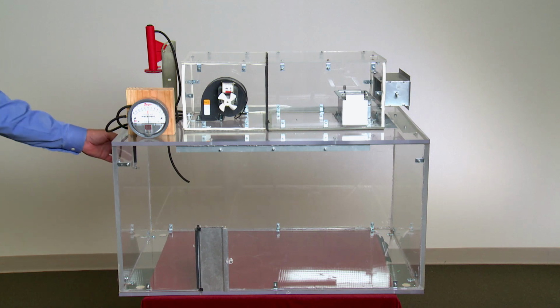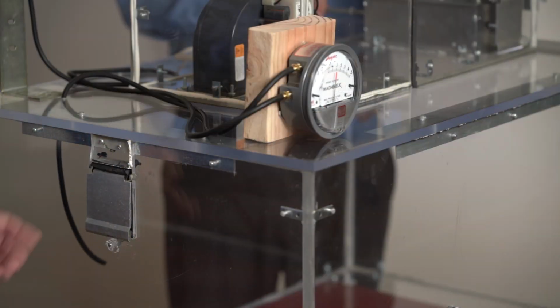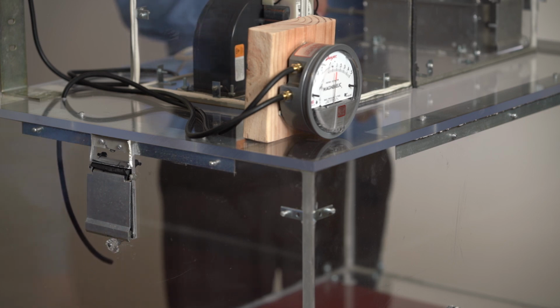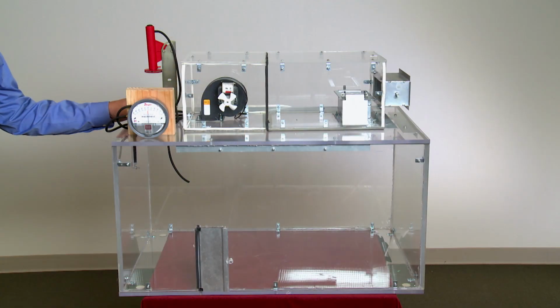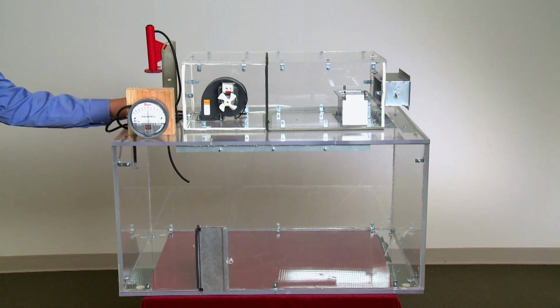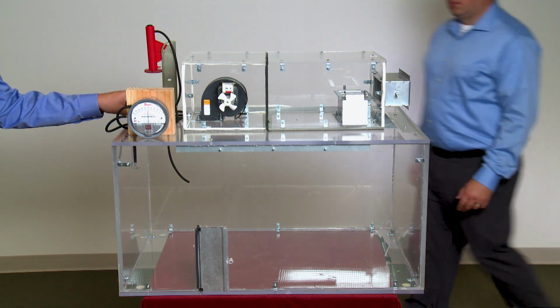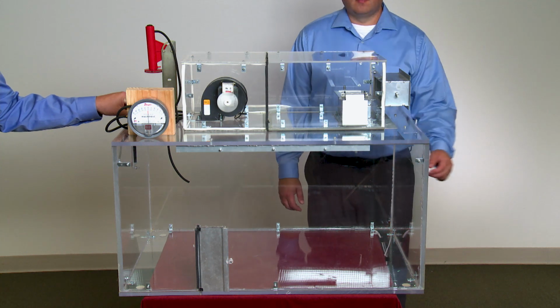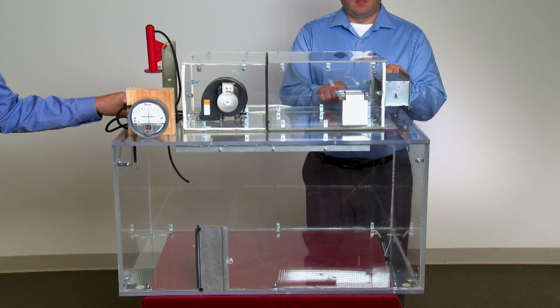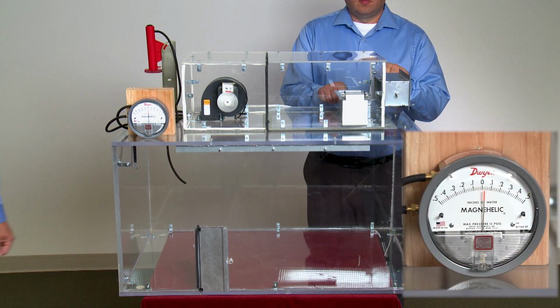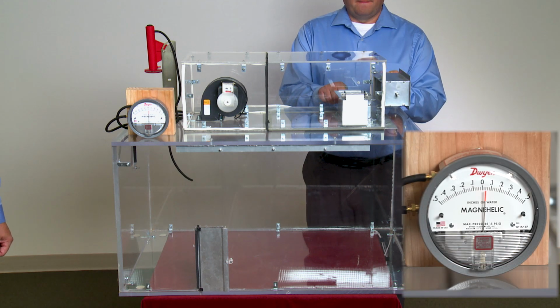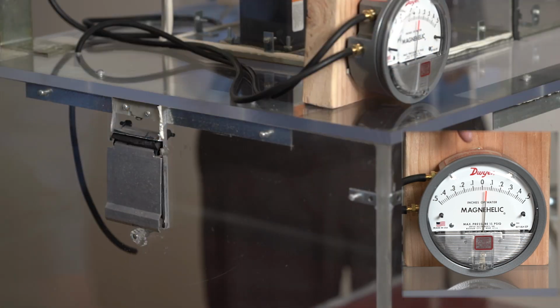Over here in the side wall of our model building, we have a real but very small barometric damper. It's hinged and counterbalanced so it hangs closed. It was latched shut for the first demonstration, but for this one I've unlatched it so it's allowed to open. To demonstrate barometric relief, we'll start the fan again in recirculating mode. That is, return damper fully open, outdoor damper fully closed. As Eric opens the outdoor damper to minimum position, again, building pressure rises a bit. Not enough pressure to force open the barometric damper yet, so right now just natural relief is happening.